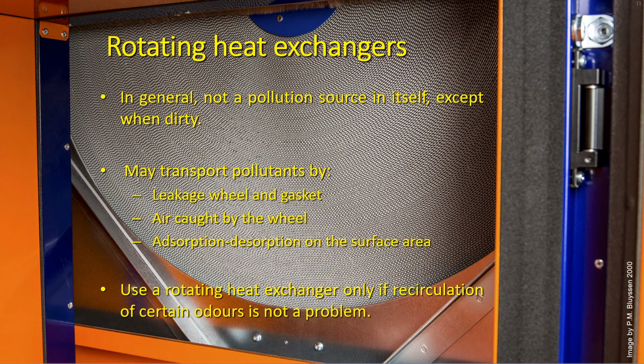If you decide to use a rotating heat exchanger anyway, and don't find it a problem that certain odors are recirculated, the following tips might help to reduce the transport of pollutants. To minimize or prevent absorption on the surface of the wheel, it is recommended to avoid the use of hygroscopic wheels, because odors and other pollutants are more easily absorbed on such surfaces.